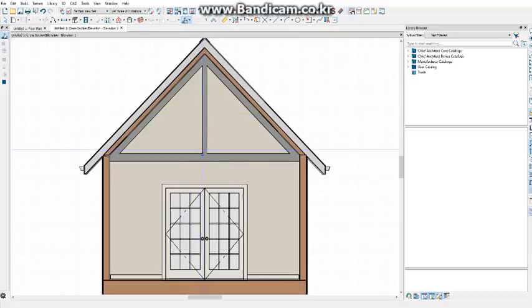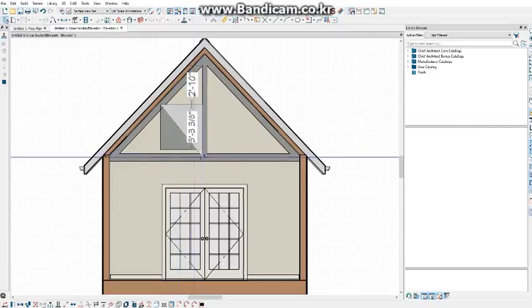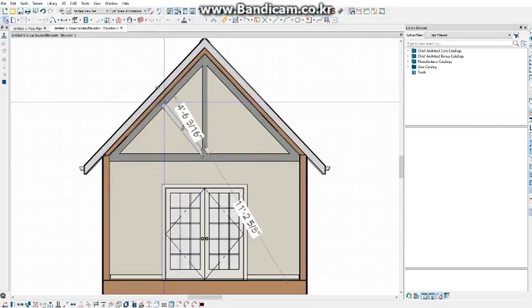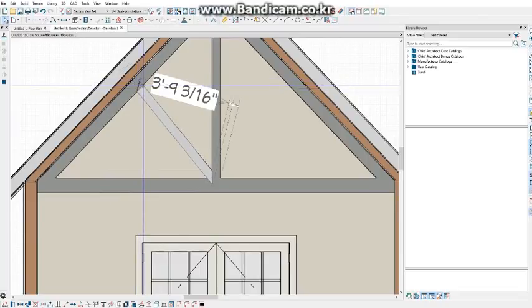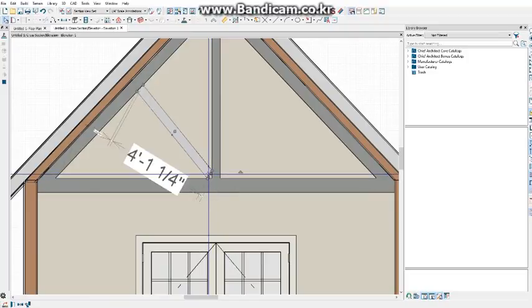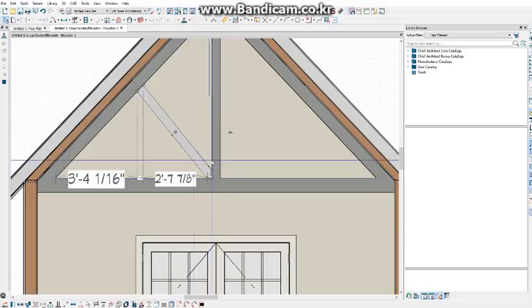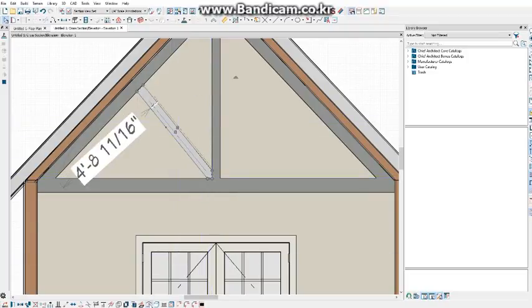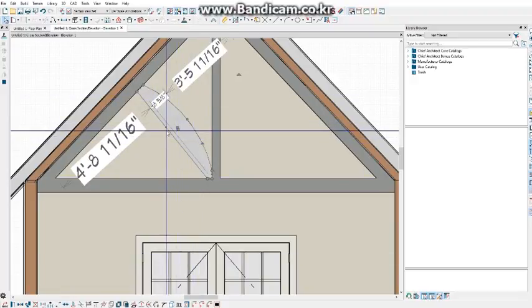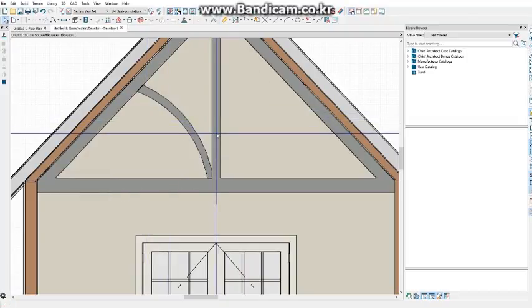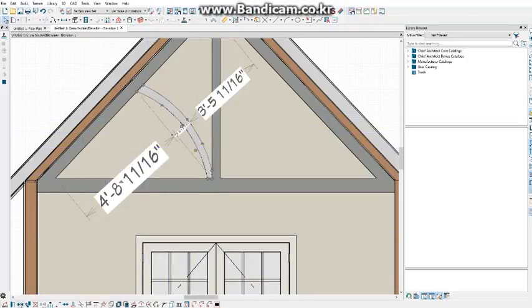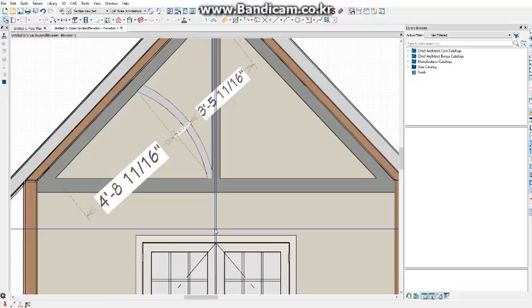Click and drag to create the polyline solid, and then use the edit handles to shape it. And then use the edit tools in the toolbar at the bottom. Create a breakpoint, fill in the corner. Use my change line to arc tool on both of these sides to arch my web piece. Select that piece and copy paste, reflect about the wall again.